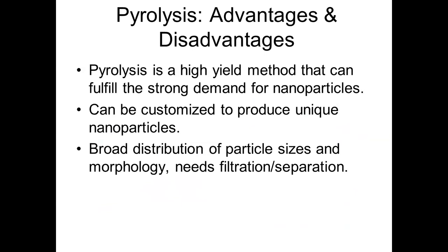So we saw we have control variables in the manufacturing method, and again, we can establish these control variables, manipulate them to get to the appropriate particle, and then lock those into place to give us a nice distribution of particle sizes. We can also control the morphology, and we can also provide further tightening of the Gaussian distribution of sizes by some filtration and separation processes.